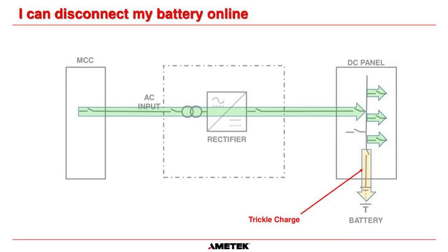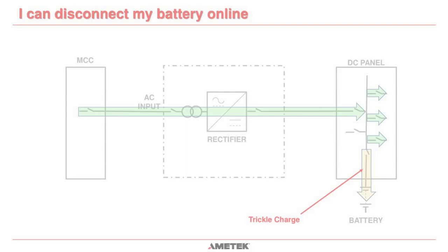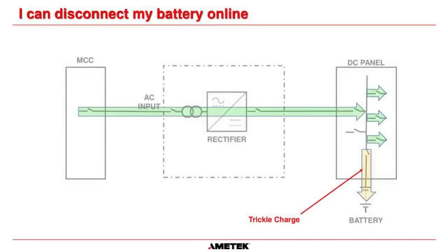Our next situation is, I can disconnect my battery while I am online. Once again, it is a misconception in many different circumstances. Let me explain why you shouldn't have that attitude. In normal operation, our charger is feeding the load circuits, and we are keeping the battery on trickle charge.